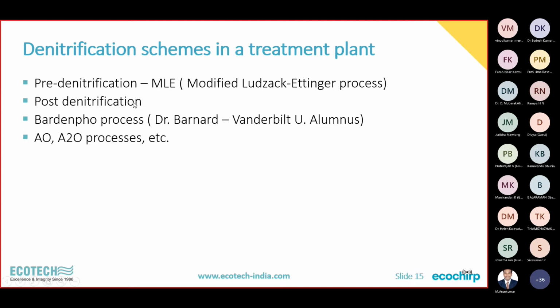Whereas in post-denitrification, it is more operator dependent. It depends on how much additional chemical he has to use and things like that. So it becomes more operator intensive. We don't prefer that. We want to keep a treatment plant as simple as possible without any operator error. So we recommend the pre-denitrification MLE treatment scheme.